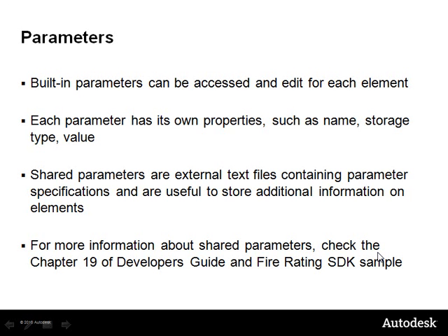In Revit, we have a mechanism to access and edit the collection of built-in parameters of each element. Each parameter has its own properties, such as name, storage type, and value. We can also use the Revit built-in parameter enumeration to access them.